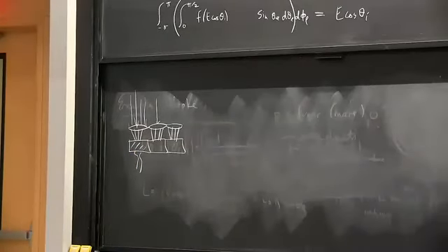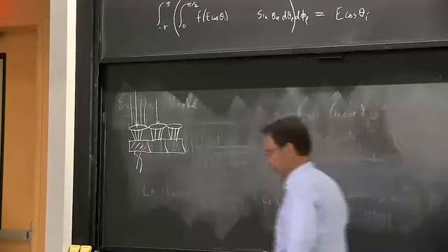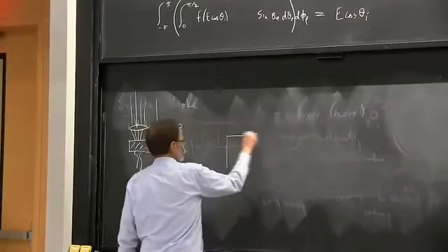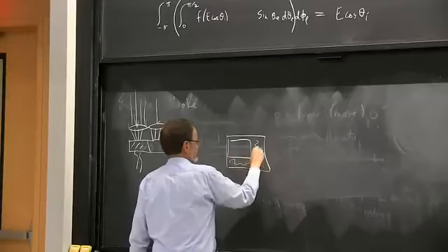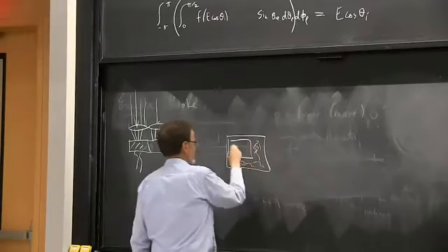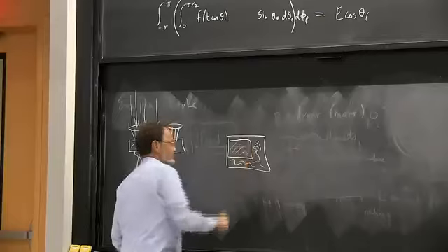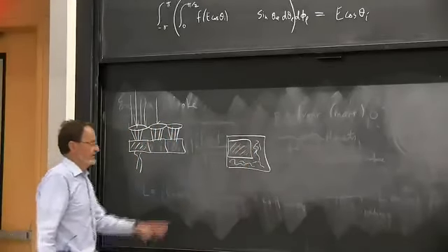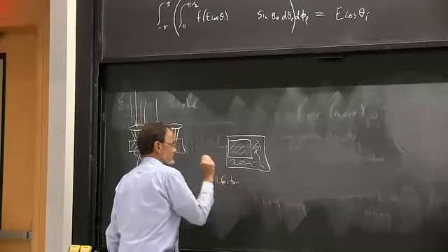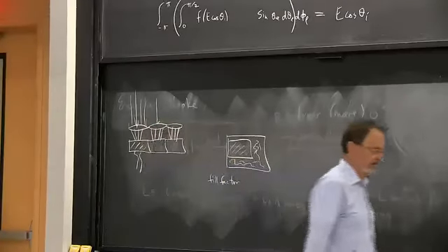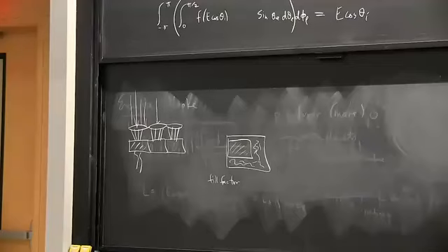And why? Well, because there's circuitry. So the surface of the sensor isn't all sensitive to light. If we look down on it from above, it might look like this. And then there's a lot of switching circuitry and stuff around it. So here's the area that's actually sensitive to light. And then there's this other thing. And there's something called the fill factor. Of course, there are many different designs, but that's something that happens in many designs.